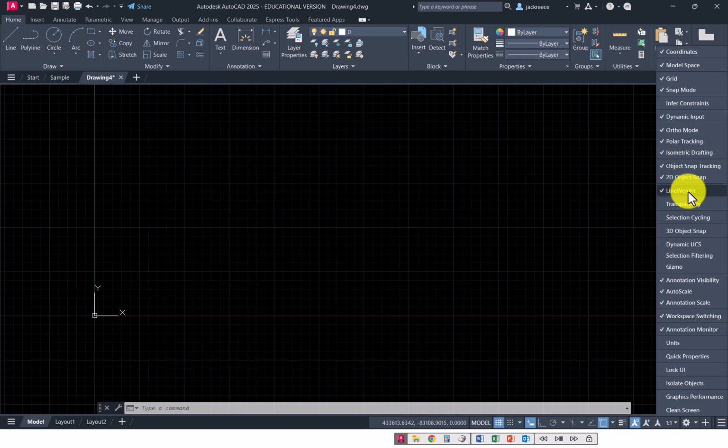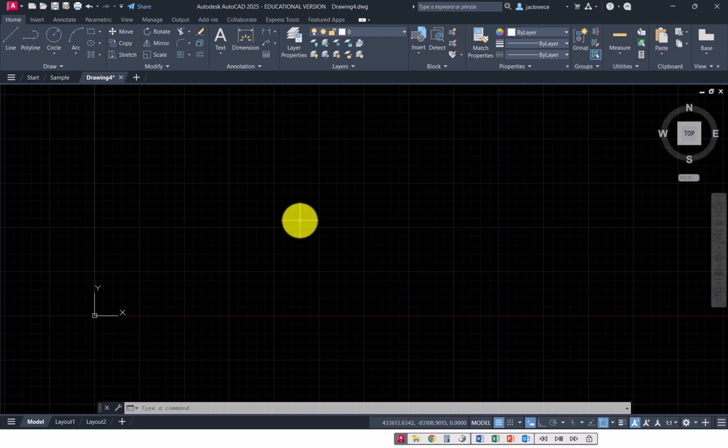The visible lines or the object lines should be thicker. And then your border should be even thicker than that. Okay, and there's other lines too that have different thicknesses. Well, what line weight does is it doesn't display the exact line thickness, but it displays it as kind of a relative.